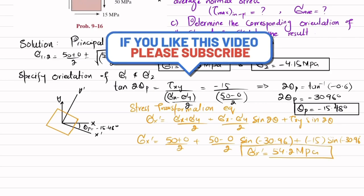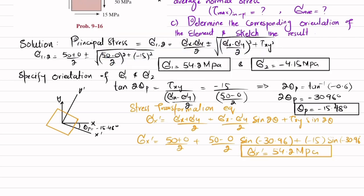Now it means that this sigma 1 is acting on this face. So your sigma 1 is acting on this face, which is positive value. Clear? And your sigma 2 is on this, and since this value is negative, so it will be compressive. Clear? This is sigma 2, which is 4.15 megapascal, and this arrow shows that this is compressive.